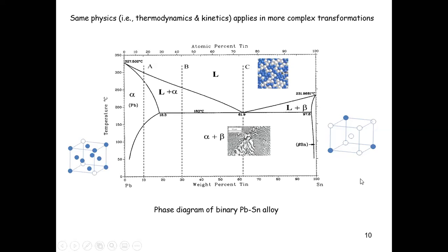That's very good. But you see that you always have to go back and forth, making connections between all this information and making it consistent. These two phases are distinguished by both the microstructure, because here you have FCC and here you have BCC, and their composition, because this is lead rich and this is tin rich. I'm sorry, this is not really BCC. This is body-centered tetragonal, but it's similar to BCC. This is tin rich, and this is liquid.